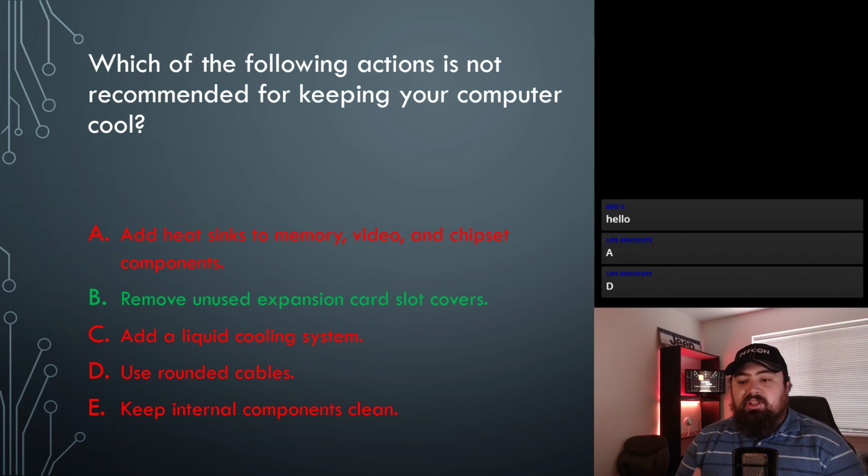When you remove system covers and expansion covers, you modify the airflow path, which typically reduces the cooling efficiency. It also can allow dust to be introduced into your system, which will reduce the system cooling efficiency. So you definitely don't want to remove unused covers.